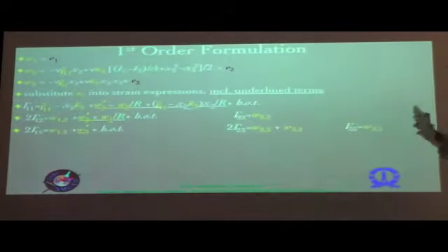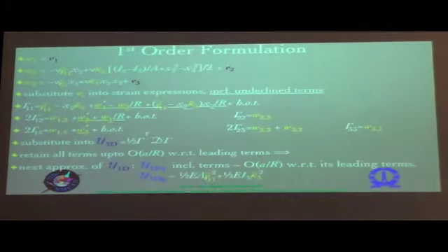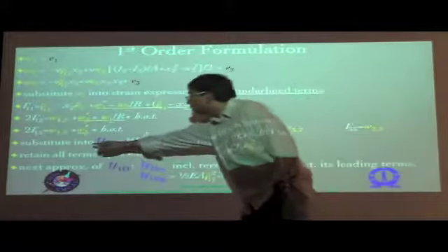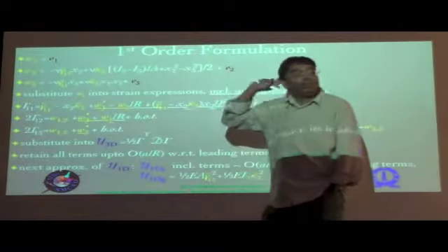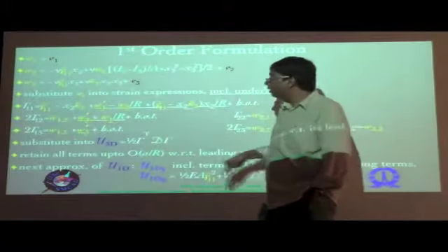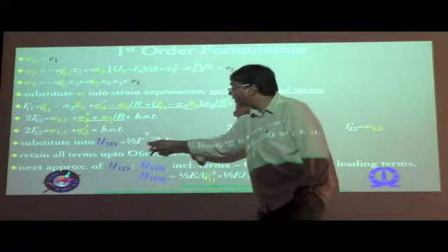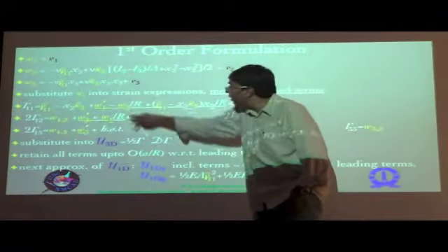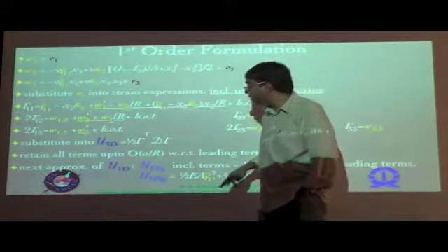So that's the case with those three. These of course are exact expressions for the in-plane strains within the cross section. Now we go to the original integrand, which is U3D, which is once again quadratic in the gammas, with these gammas as the expressions for it.